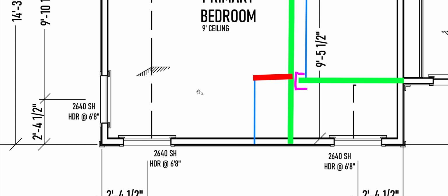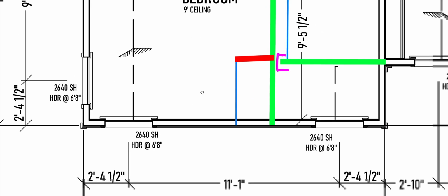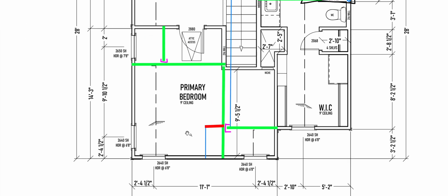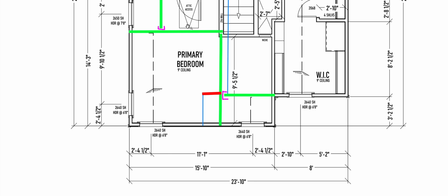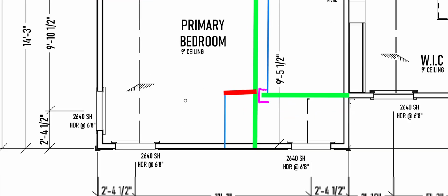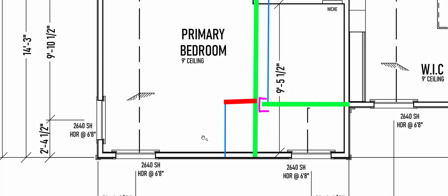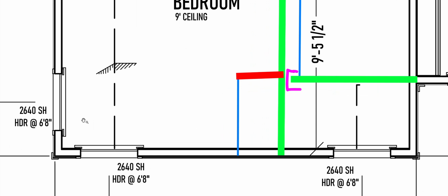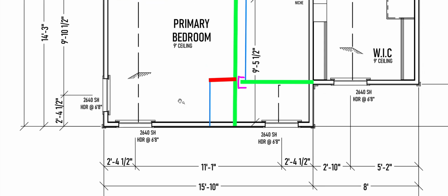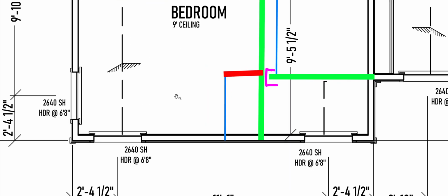The reason I want to use 12-inch on center spacing is it's really not going to disrupt my 24-inch on center spacing on the rest of the roof in terms of the numbers and the dimensions. So I'm basically going to start adding in rafters, and for each one of those that I do, I'm also going to double the ceiling joist.